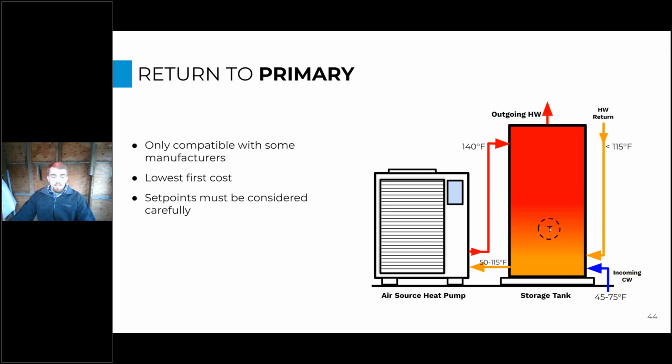In a stratified storage tank with a separate temperature maintenance load, you might turn the heat pump on when this temperature sensor reads 100 degrees, because that's when the cold water hits the temperature sensor. But if your hot water return temperature is 115, now your tank's filling with 115 degree water if you don't have a lot of hot water usage and cold water coming in. So now your heat pump's not actually going to turn on. So you have to be really careful with those control set points and have the manufacturer rep help you pick those out.